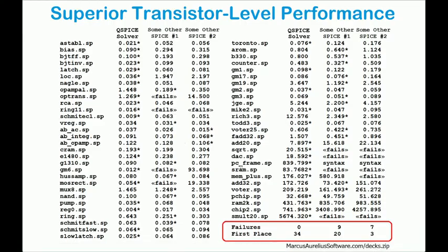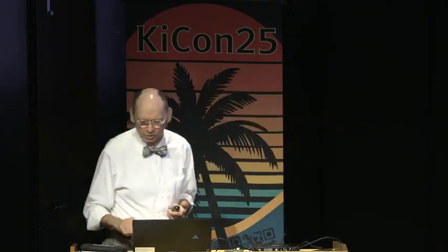They're not some contrived benchmark that I did to make QSPICE look good. QSPICE is the first simulator I've ever seen that can run every single circuit. These circuits were collected and they found discontinuities in the curves. They didn't work for reasons they didn't understand. They just collected in academia, saying we can't solve this IC. QSPICE can solve every one, and they do preposterous things like charge pump the substrate node off into voltages beyond the rails, and they're difficult circuits to solve.